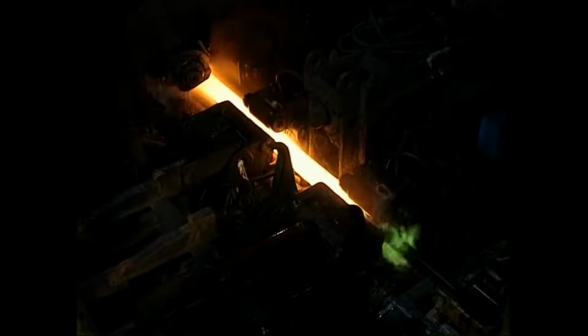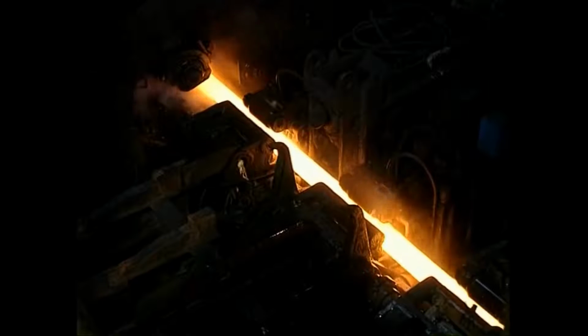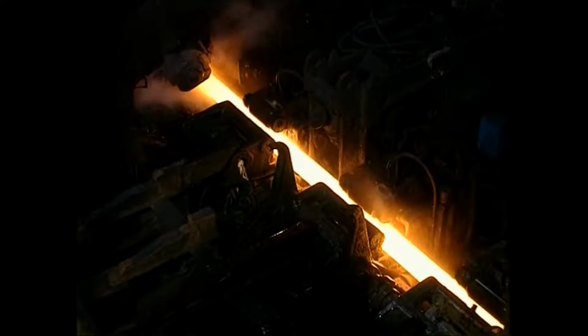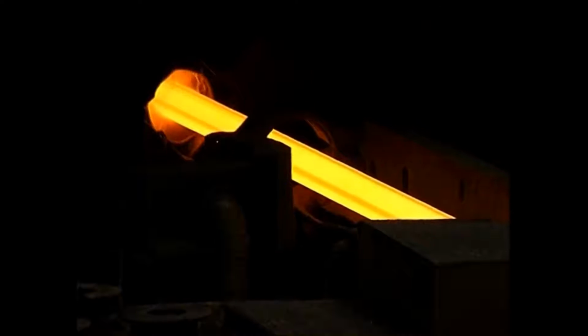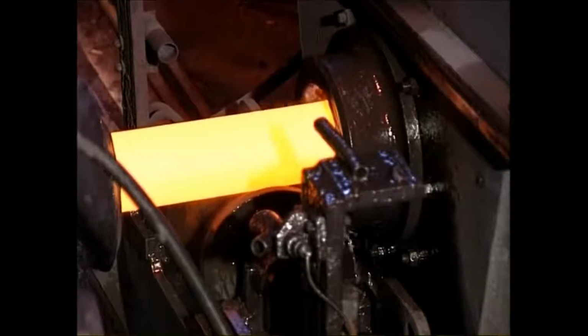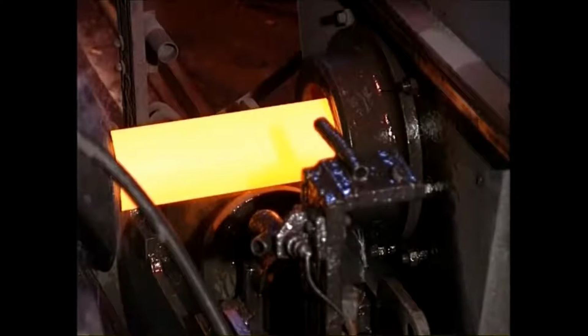To make a seamless tube, you must first bore a hole through a hot billet, either in a large press or by rolling the billet through special piercing rolls. The hollow billet is then stretched over a bar, which enables the interior of the tube to be sized. For both types of tube, a final sizing operation can take place, slightly reducing the outside diameter to the required dimensions.